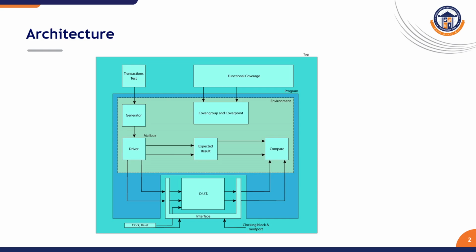So the environment is where the class instances are presented along with their connectivity. Now on top of the execution of verification using OOPS concepts, SystemVerilog also offers functional coverage, which we will see in different videos. You can say that all the test cases have been covered when you have 100% functional coverage. Code coverage tells us about the result achieved from the test cases generated from the stimulus.